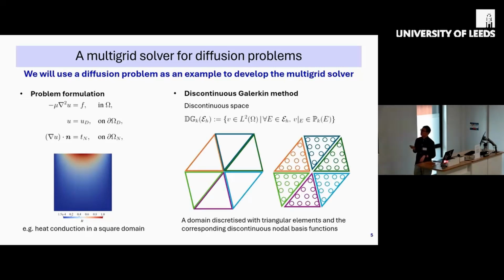So the discontinuous Galerkin method works as shown in this illustration here. On the left is a Hessian domain that we want to solve our problem on. In this illustration, we do a triangulation, using 6 triangles to discretize the domain, and then for each of the triangles we have a subspace on this triangle, with several nodes or degrees of freedom inside each element.